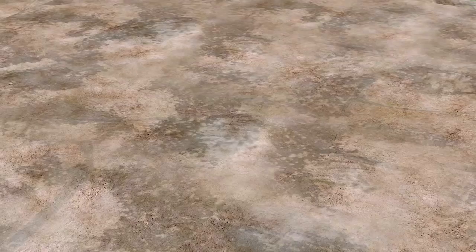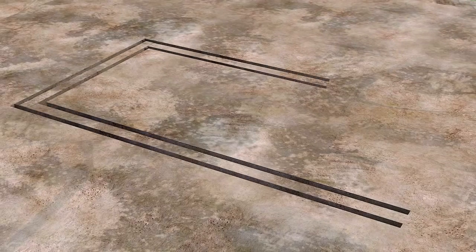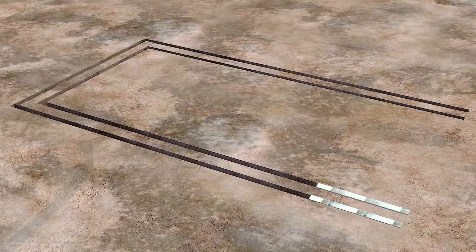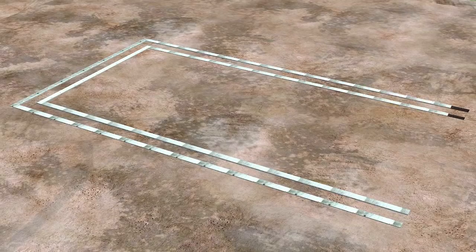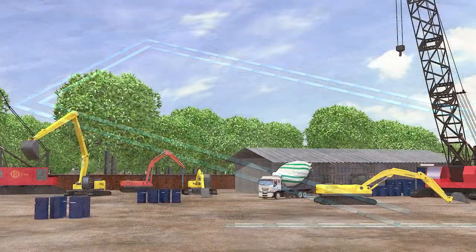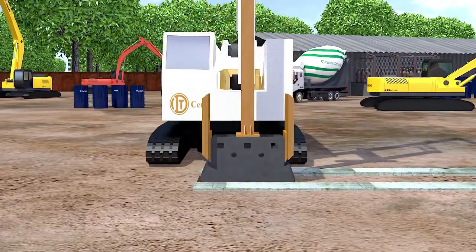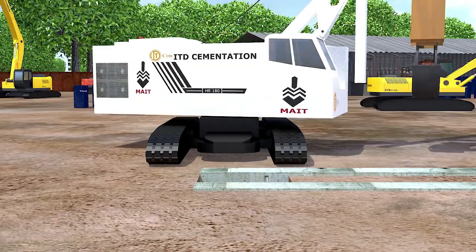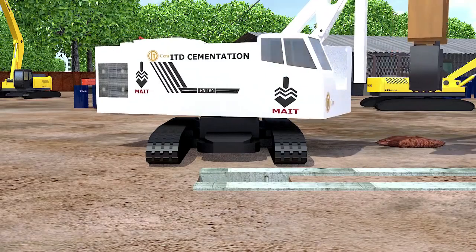To commence the first tunneling drive from Subhas Sarobar site, the cut and cover methodology is adopted. First, a guide wall is constructed to define the exact layout of the diaphragm wall, commonly known as D-wall. Excavation for each D-wall panel is done using a hydraulic rig to a depth which depends on design requirements.